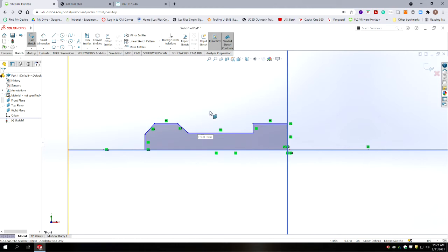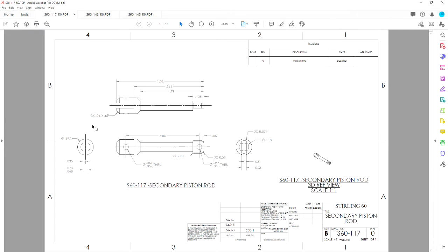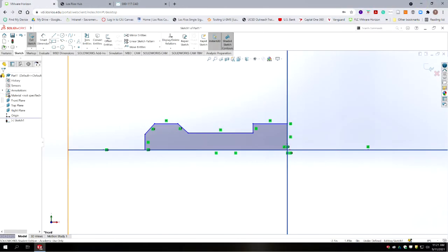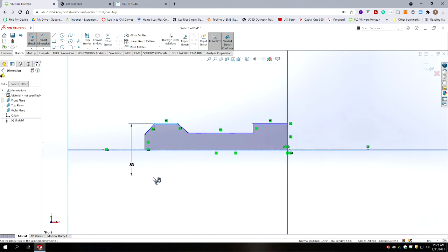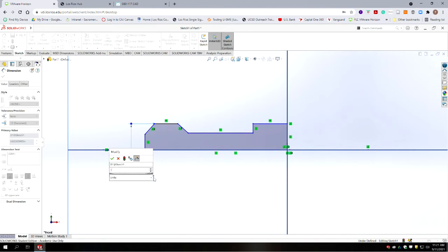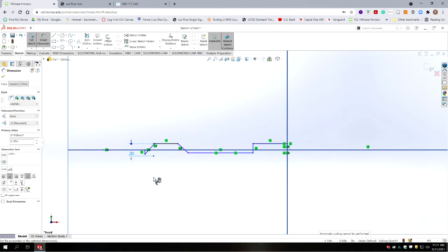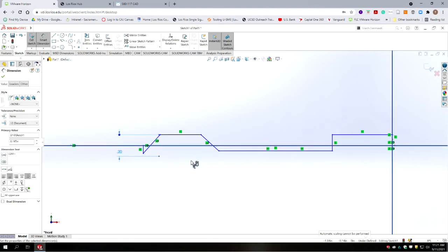So we'll start with the largest diameter, which we have is 197 thousandths. So we'll take the dimension, we'll go from the edge that was called to center line and down, so 0.197. Okay, it shrank down quite a bit because I drew the part too large a scale.